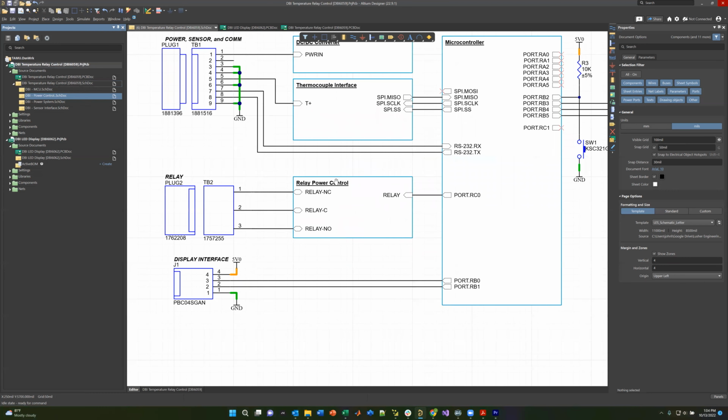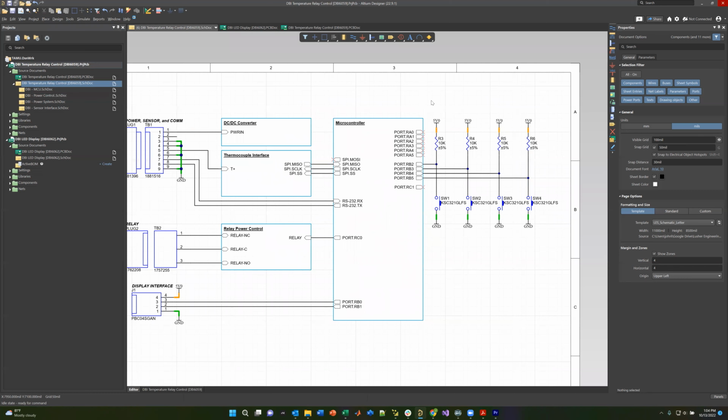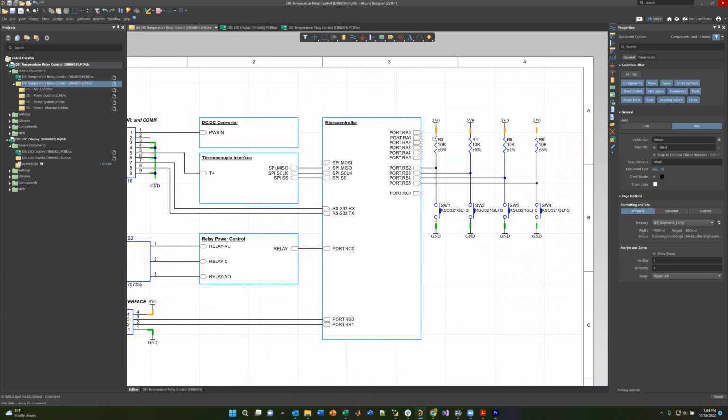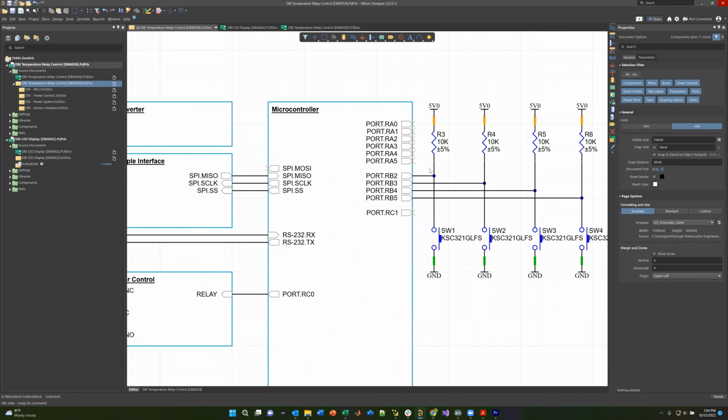So now that leaves us the microcontroller mainly. Connected to the microcontroller, we've got 4 user switches. So we've got 4 pull-ups connected to 5 volts DC. Pull-ups, by the way, will basically work because there's no current flowing into the microcontroller. The microcontroller is just monitoring the voltages. So 0 amps are coming in. If there's 0 amps going through a resistor, the voltage drop across said resistor is 0 volts. So the voltage here at this node is 5 volts if the switch is not pressed.